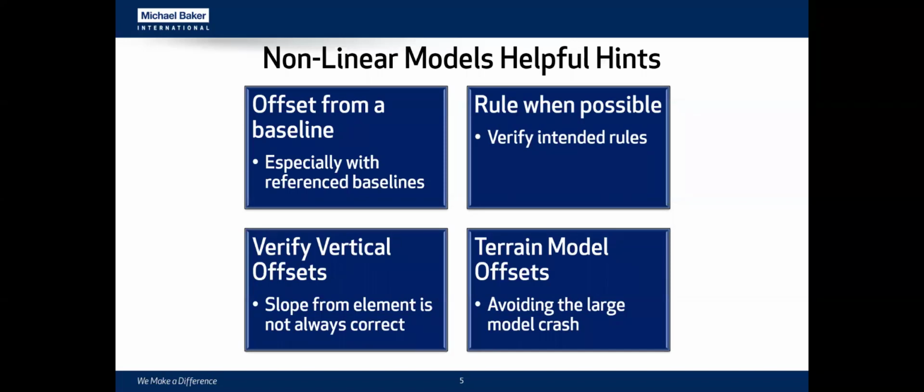And then your terrain model, you want to make sure that you're avoiding overly large models. If you get models that are over probably about 20 gigs in size, or you're starting to push boundaries, you're probably going to have problems. So a roundabout can be a fairly large model. Some of these complex intersections can end up being quite complex. File sizes are going to be important. And things like that.